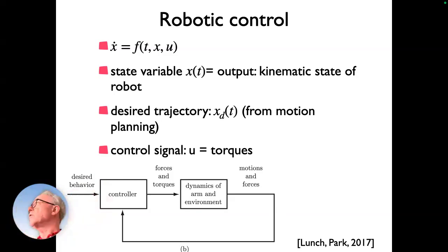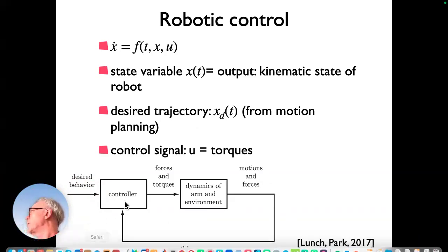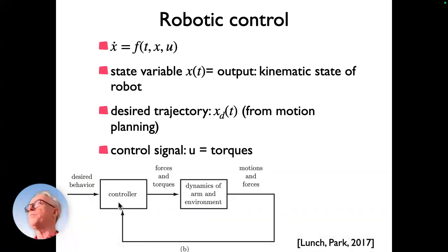And now you have to set up a control law that, given that trajectory, tells you what commands to give to that robot arm. As I just said, you can think of that command as a torque: you send a desired torque to the motors, and to a good degree they will realize that desired torque. Any deviation that leads to the motion not being exactly as you want is then compensated for by the control law that we're now going to think about.